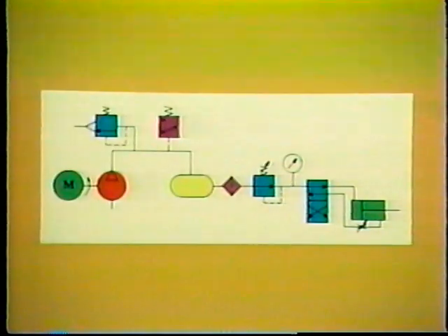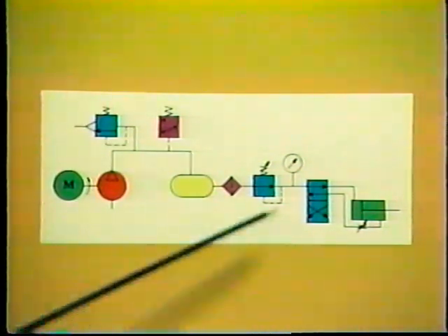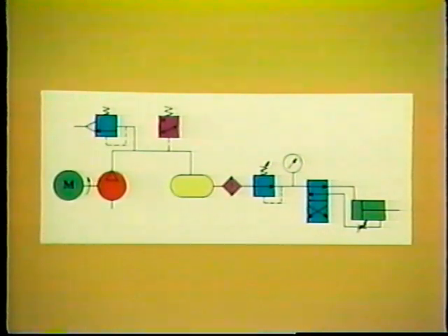Okay, before we finish, let's see how that basic pneumatic system looks when we substitute the symbols for the pictorial illustrations. Here it is. Can you identify the compressor? It's right here. Or the air receiver tank? This is it. And how about the double-acting cylinder with flow control valve? If you said this is it, you're right on target. Well, you'll find the more you use these symbols, the easier they will be to remember. Now turn to page 34 of your text and do the exercises that you'll find there.